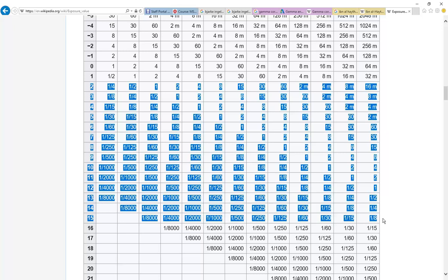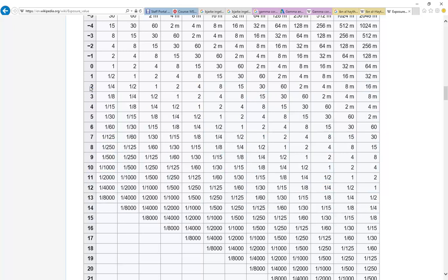So we want the most control of sunlight, or of light, because we've got a lot of light that's going to make things really bright. By setting it to 15, we're going to limit the amount of light, which is going to control all of that bright sunlight. In an interior that's rendered with minimal artificial lights, you might only need a value of 2. You'll very rarely go below 2, because that's for really low level lighting, 1 and 0.